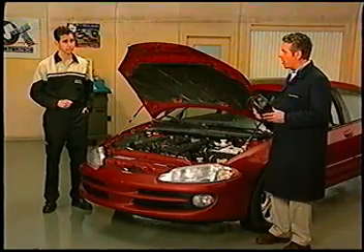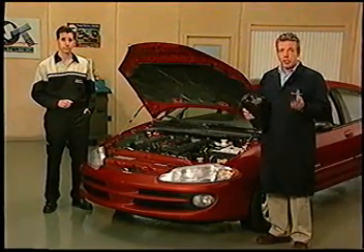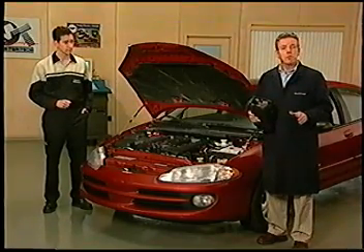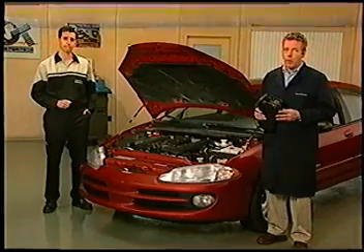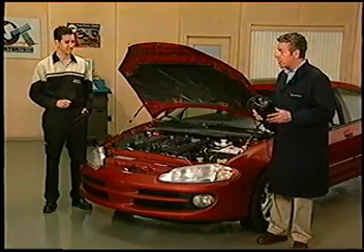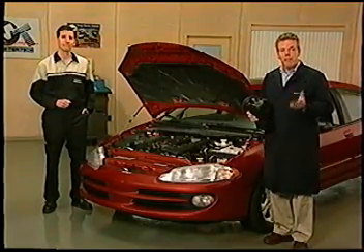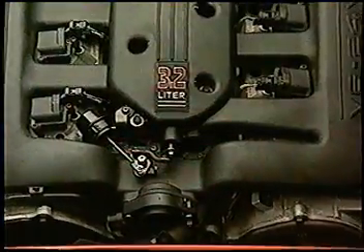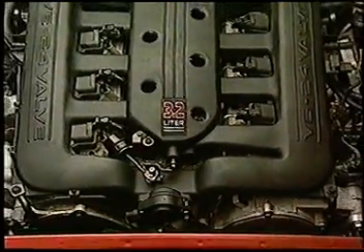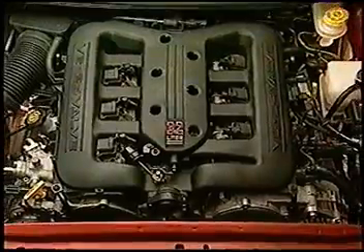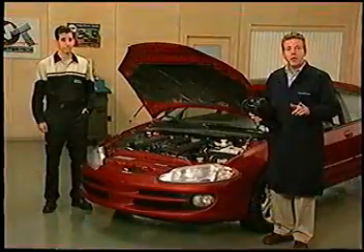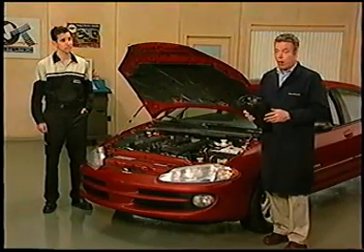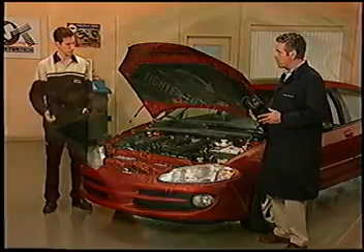Well, you're off to the right start. Anytime you suspect there's a leak in the evap system, you should always perform a thorough visual inspection before replacing or even disconnecting any components, just as you did. Sometimes disconnecting connections can actually mask a leak condition. Also, on vehicles having a leak detection pump, like this one, in some instances you can get a leak fault when there's really nothing wrong with the system. For this reason, there's a couple of items that you need to be aware of during diagnosis. Like what?